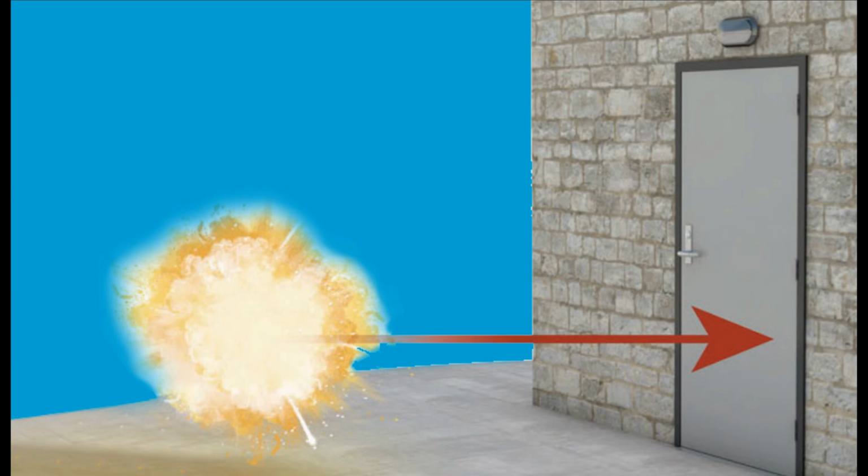That multi-point lock is only one option. I don't like what we have online, because yes, that multi-point lock is an option, but if the blast levels are less, I can go all the way down to a mortise lock. I mean, the door that's in the room that you're in right now, you can run into it with your shoulder, and odds are it doesn't pop open.